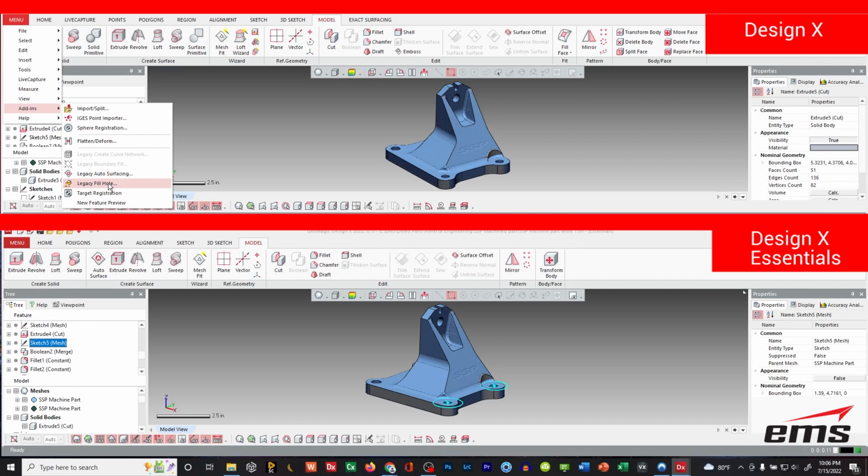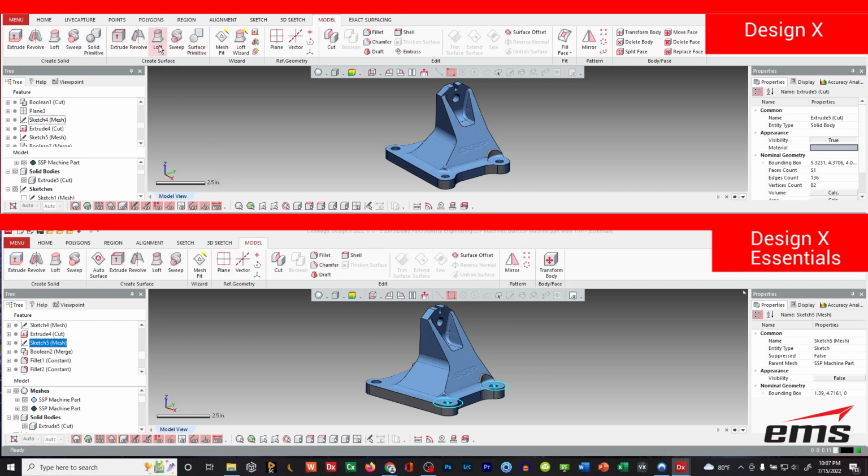They work a little different, and sometimes I like the results for those. So keep that in mind. You do have Mesh Fit Surface. That's where you kind of suck a surface down to a shape. Great for things like impellers and things that just have a big curved surface. It is a nice tool to have. So again, none of the wizards.